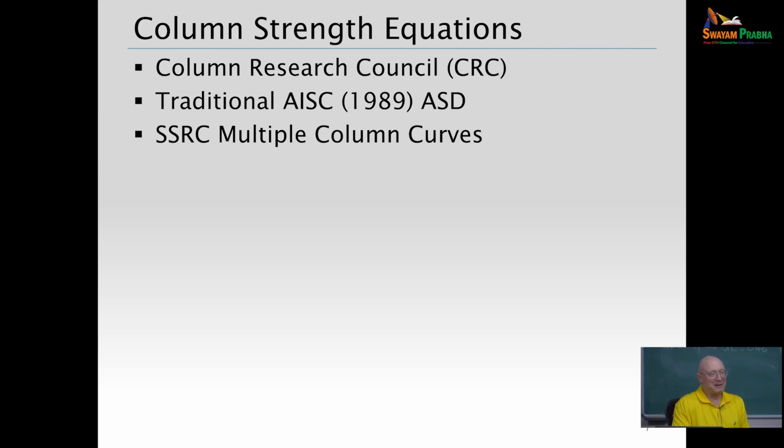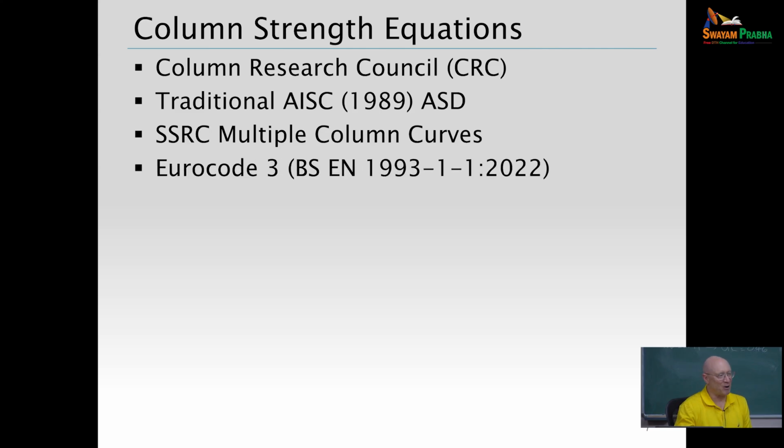And even now, in the technical committees at AISC, we are discussing quite intently, particularly nowadays, instances where we want to use very high strength steels. You pay a huge penalty if you don't use a different column curve if you go to a higher strength steel. So at least for that, we at AISC have some traction that, yeah, we should have maybe two column curves. You can still make arguments for the others, but it's a hard sell in the AISC committees.